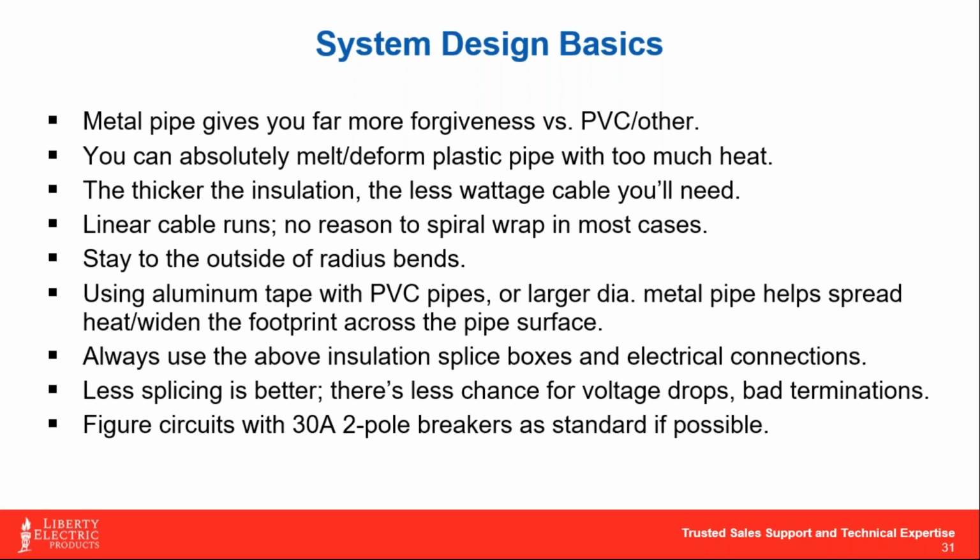Your heat trace cable is really only going to be about a 1/2 inch to 3/4 of an inch, and it's more like about a 1/2 inch wide. So if you can imagine 3 1/2 inch wide runs down a 12-inch diameter pipe, again, you've got heat in a 1.5 inch footprint, and you've got 12 inches you've got to cover.